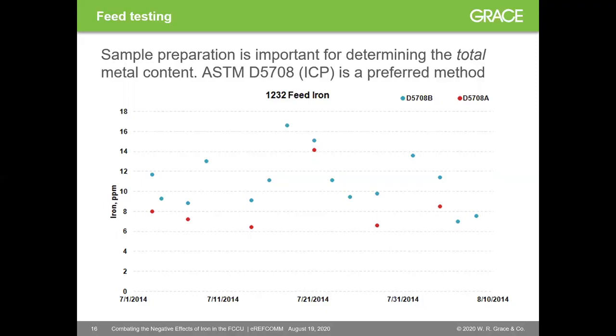The acid digestion method, method B, will measure the total metal content, whereas the solvent digestion method A will detect metals present in the insoluble particles. The total amount of iron showed roughly 30% higher in the acid digestion method. However, it varied over the course of the samples. Use of this method helped close catalyst balances and help drive resolution steps.